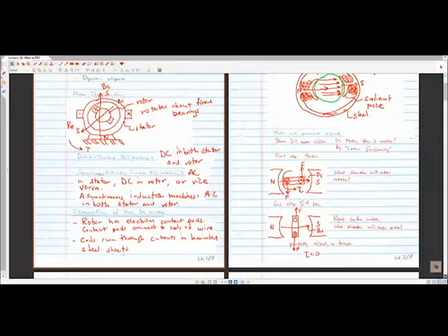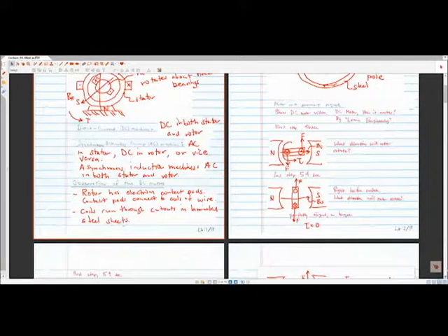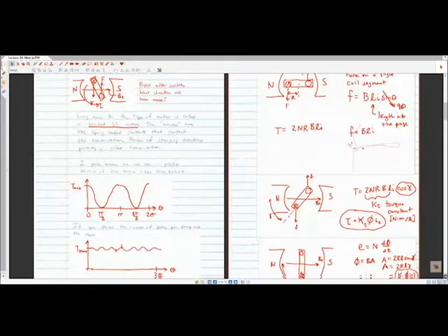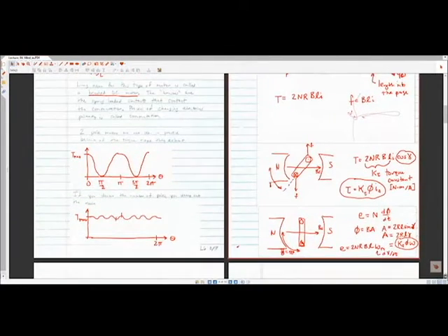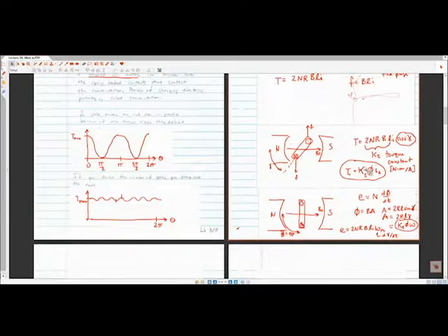So what we then did after we introduced those basic structures of a system is we talked about the torque you get from a DC motor, and we went through a little bit of math, and we got down to this expression that the torque is equal to the torque constant times the flux in the system that's coming from the stator, times the current running through the circuit that is in the armature, or also called the rotor. All right, so this is K tau times phi being the flux times the current running through the armature.